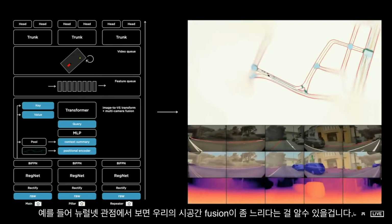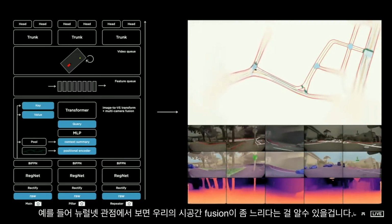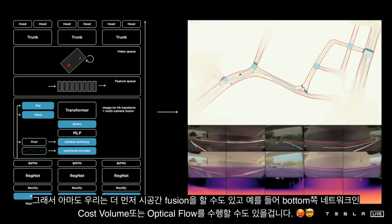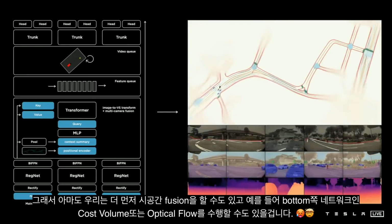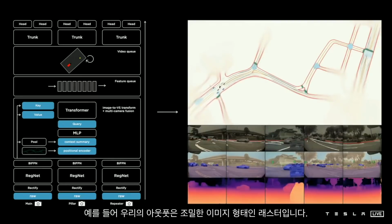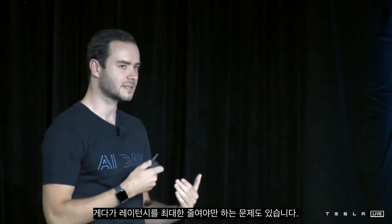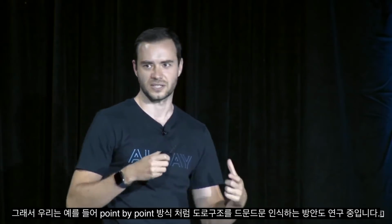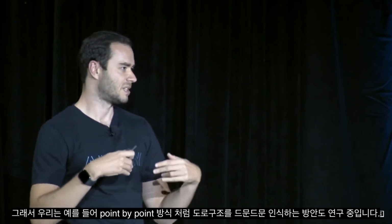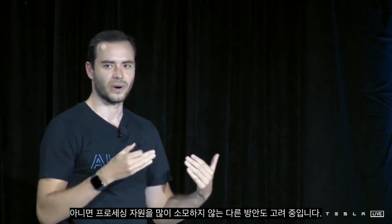For example, you'll notice that our fusion of time and space is fairly late in neural network terms. So maybe we can do earlier fusion of space or time and do, for example, cost volumes or optical flow-like networks at the bottom. Or, our outputs are dense rasters, and it's pretty expensive to post-process some of these dense rasters in the car. Of course, we are under very strict latency requirements, so this is not ideal. We are looking into all kinds of ways of predicting just the sparse structure of the road, maybe point by point, or in some other fashion that doesn't require expensive post-processing.